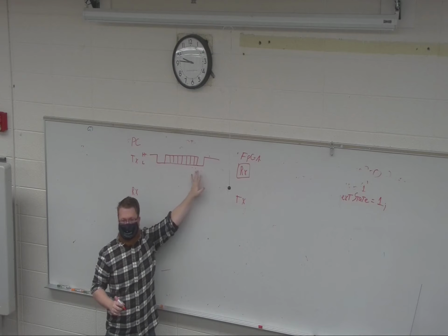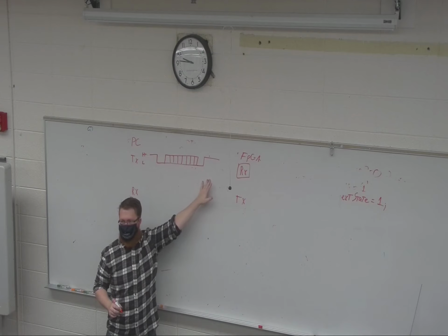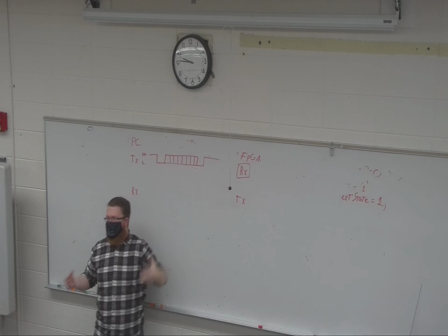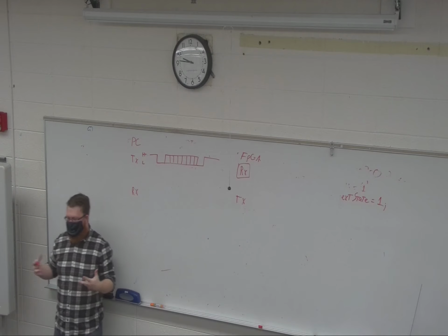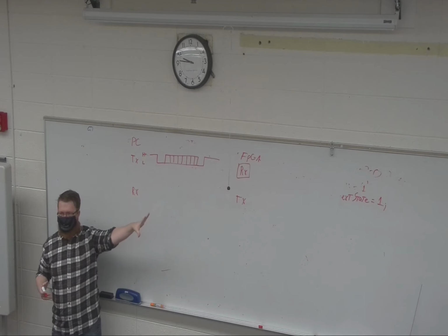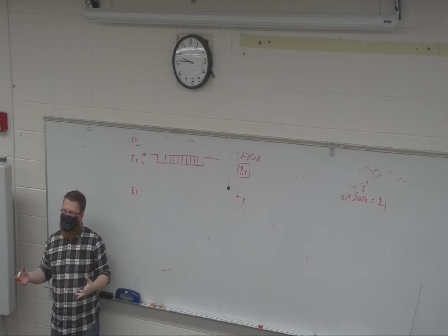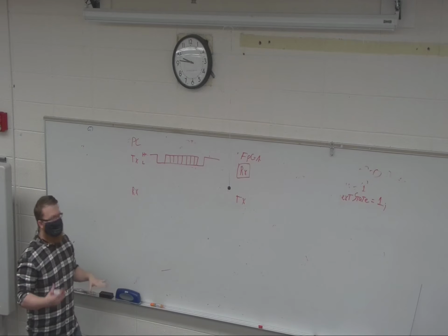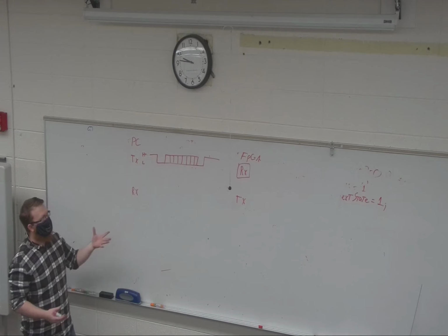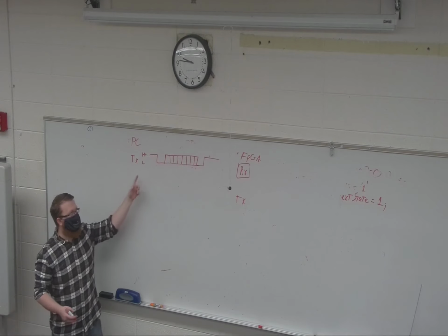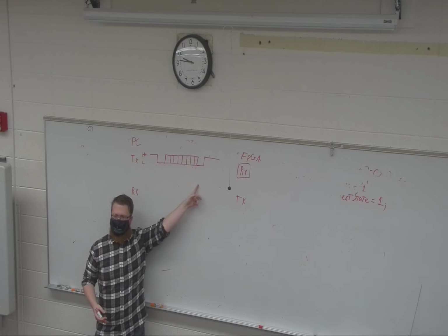There is an optional something we call a parity bit. The idea of the parity bit was from a time when UART channels were really bad and we were not very good at this stuff yet. We wanted a way of checking the data integrity. The simplest way of doing that was to have a parity bit that would basically count up the number of ones in the transmission.